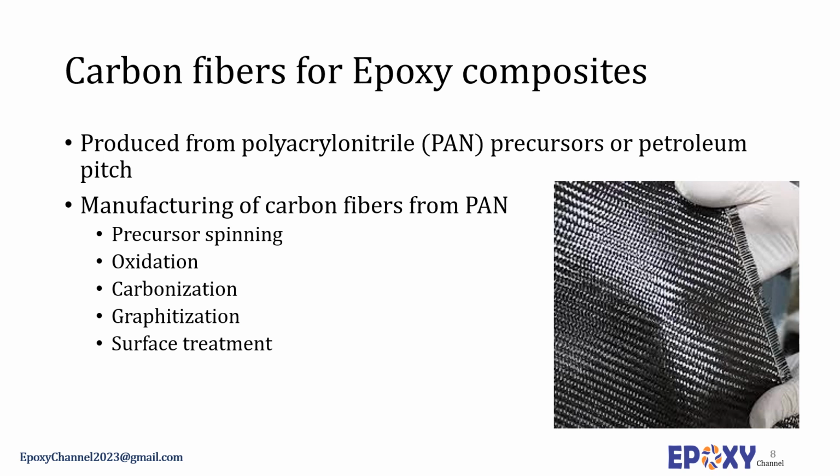High-strength carbon fibers are also manufactured commercially from petroleum pitch. This process involves the polymerization of the condensed aromatic molecules at temperatures above 350 centigrade for extrusion melt spinning into fibers, thermosetting in air, and carbonization at temperatures around 2000 centigrade. The main difference between these two carbon fibers lies in their microstructures. The pitch fibers tend to have radiating crystal structures, which yield a lower transverse strength than for PAN-based fibers.